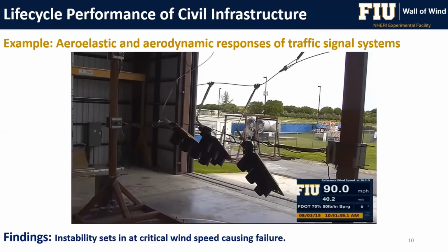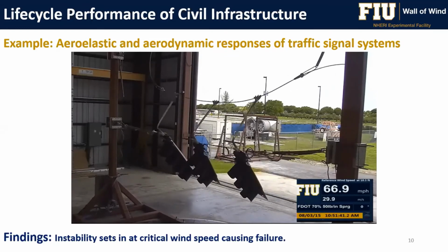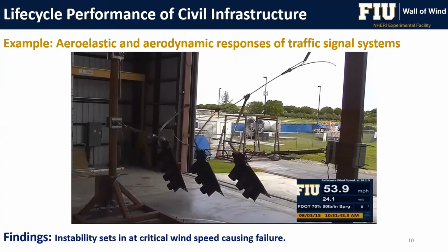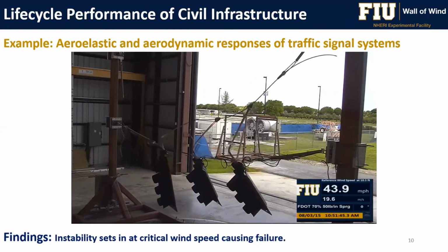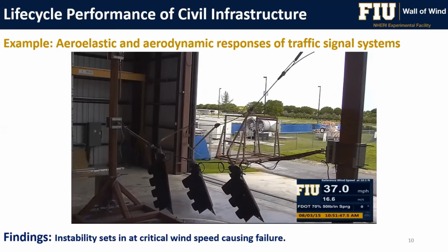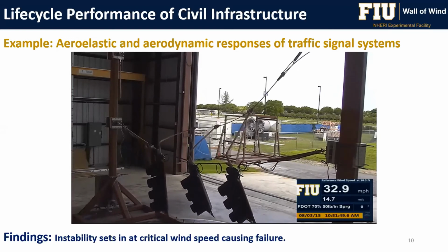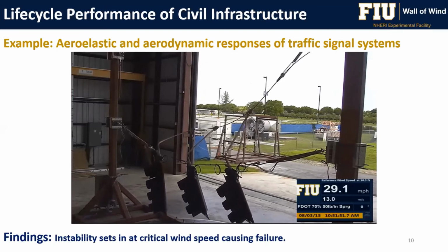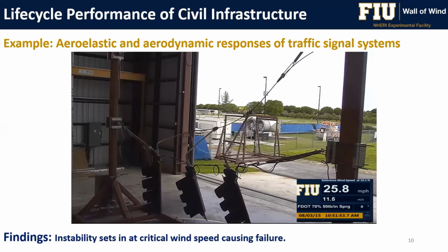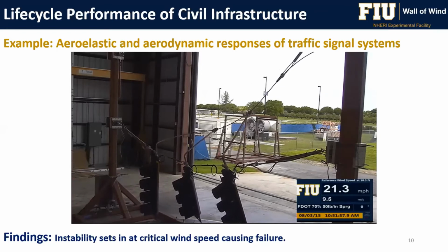So here at the Wall of Wind, you can do these kinds of testing, which is not always feasible in a smaller wind tunnel. You can look at the infrastructure performance at full scale, and you can measure the effects of the wind in terms of forces, moments, strains, accelerations, and things like that.